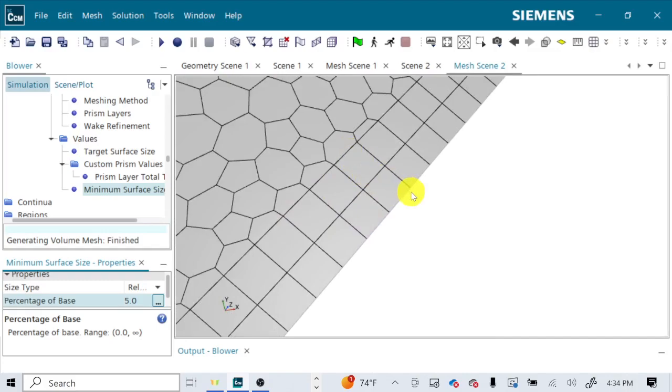And we might want to turn down that prism layer thickness a little bit. You see this? This is a sign, I mean, we're basically not stretching the prism layer at all. This is a little bit of a size jump. We can fix that a little bit. We make the prism layer like 25% thick, I think. Or we don't need to constrain ourselves to factors of 2. We'll do 30% thick and see what that does. But if we make the prism layer a little bit thinner, these will agree a little bit better.